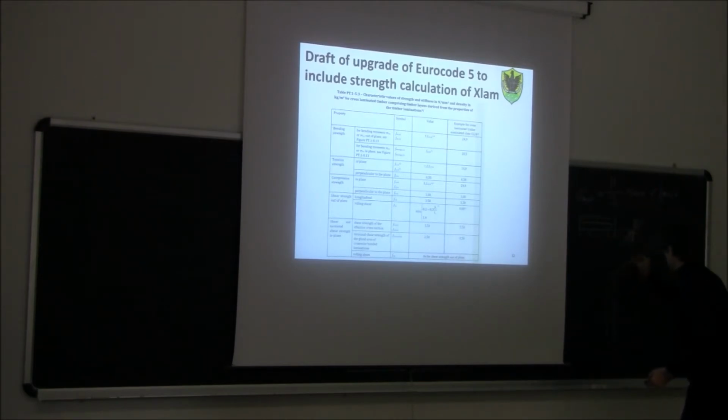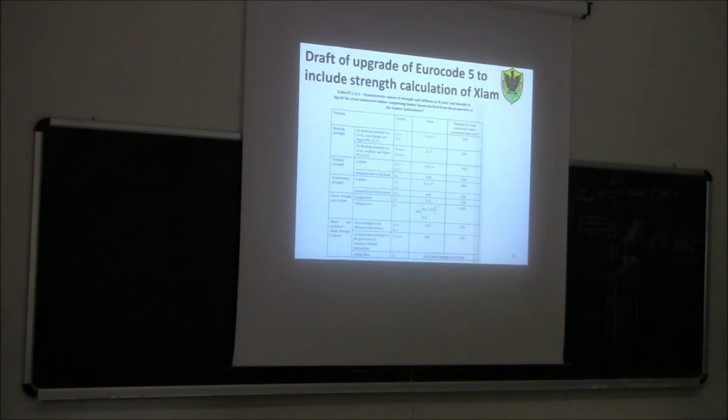Suppose we have 3 layers. So you have a situation like this: a cross-slab wall subjected to an axial force. How can you do the verification? We said yesterday you have to consider as a resisting cross-section only the layers that are oriented parallel to the stresses. Stresses induced here will be like this, so our resisting cross-section will be only this.